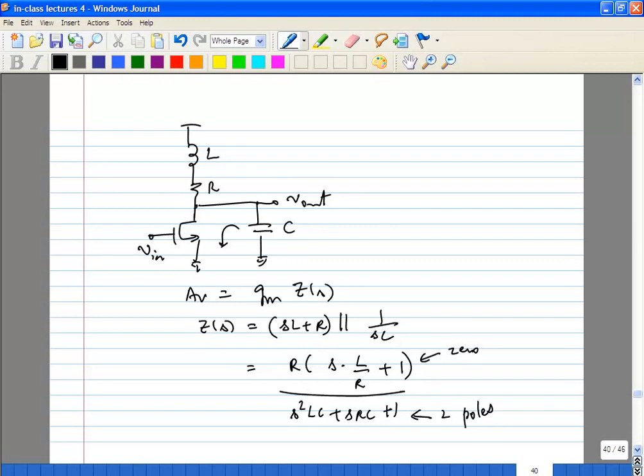What you want to do is minimize die area, which means you want to maximize the amount of inductance for a given area. So in this case you will probably be using very thin lines for the inductor. Typically thinner lines will give you more inductance, and you can minimize the area. Quite common is having multi-layer inductors, except not in shunt but in series. You wind the inductor on one layer, go down, wind it in the same direction so that it adds magnetically, and keep doing it.